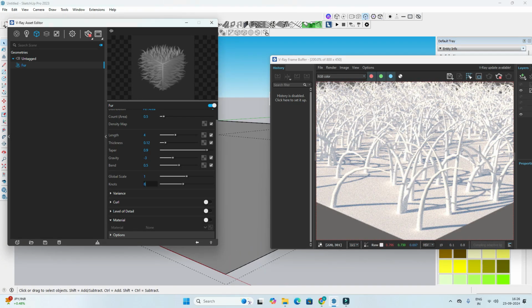Don't go here and apply 30, 40, 60 like that, because if you are giving more segments, you will get a smooth surface. If you are getting a smooth surface, the file size also will increase and the system also will take more render time. Okay now, because you are giving more detailing, right? So that is the reason render time also is going to increase.